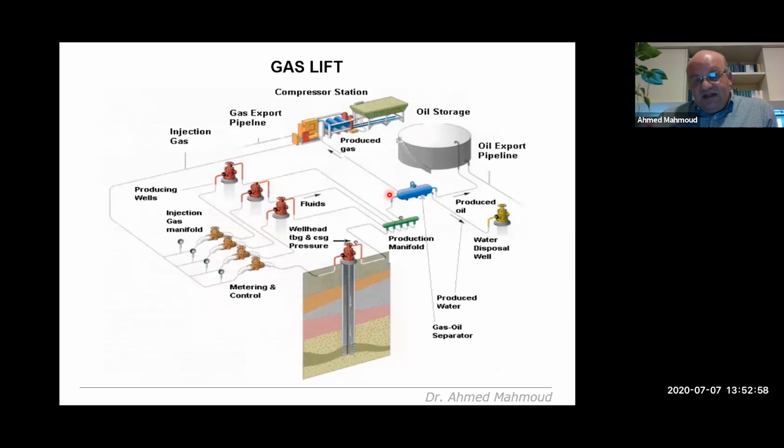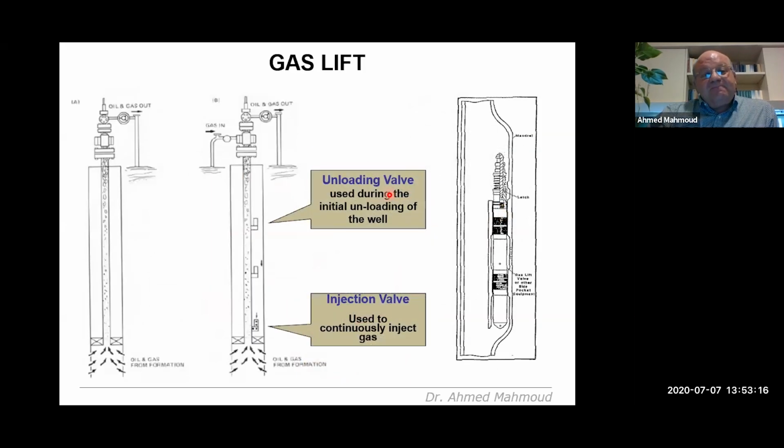You need to have a big field, about 200 to 300 wells, to have enough gas to pump and motivate the decline of pressure to mobilize a much higher fluid column. If we take this as a gas lift completion well, you pump gas in the annulus, and when you start pumping gas in the annulus, this is the magnification of the actual gas lift.